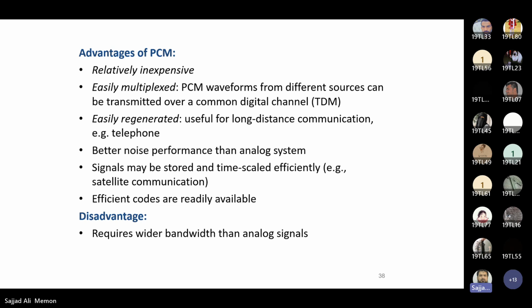Then advantages of PCM: relatively inexpensive, easily multiplexed. PCM waveforms from different sources can be transmitted over a common digital channel, that is time division multiplexing.